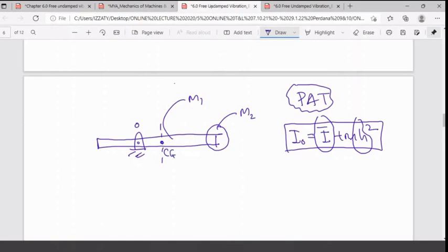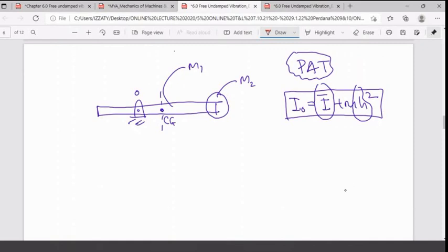Okay, and what is the H? H will be the distance from the axis of rotation to the center mass, and these two lines must be parallel. That's what they call the perpendicular, what? Parallel, sorry, parallel axis theorem. It's not perpendicular, sorry, it must be parallel. And this one we call H. This was your H. These two lines must be parallel.